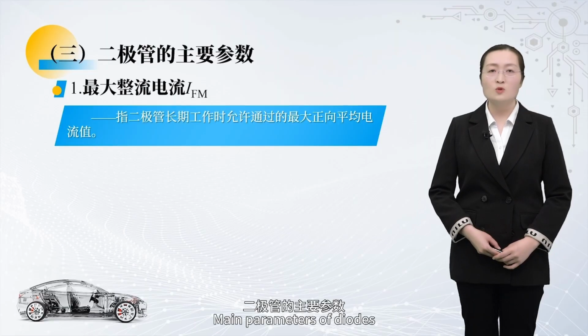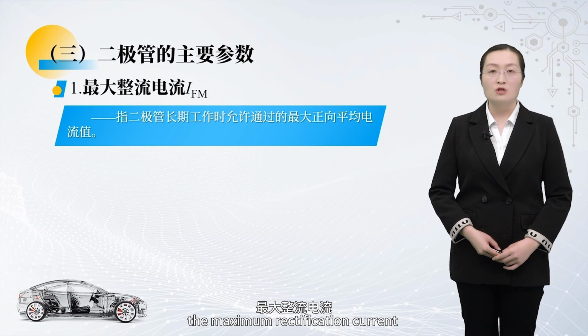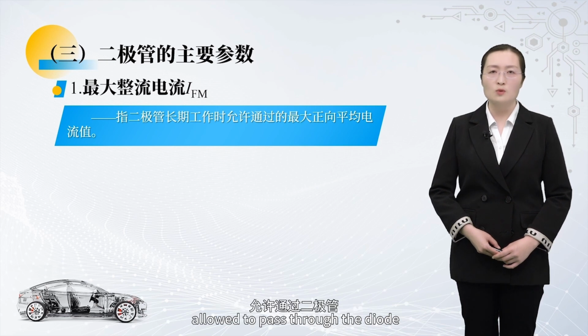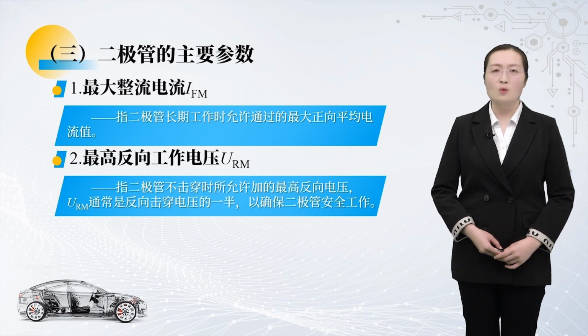Main parameters of diodes. First, the maximum rectification current, IFM, refers to the maximum forward average current value allowed to pass through the diode during long-term operation.